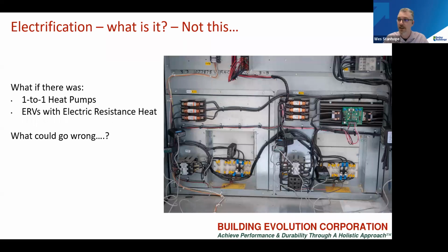In this case, the electric bill for these ERVs is about $15,000 a month. It was actually overheating apartments, which then go into cooling mode, so you have simultaneous heating and cooling, not the type you want for heat recovery in a building, but the type that costs a lot of money.